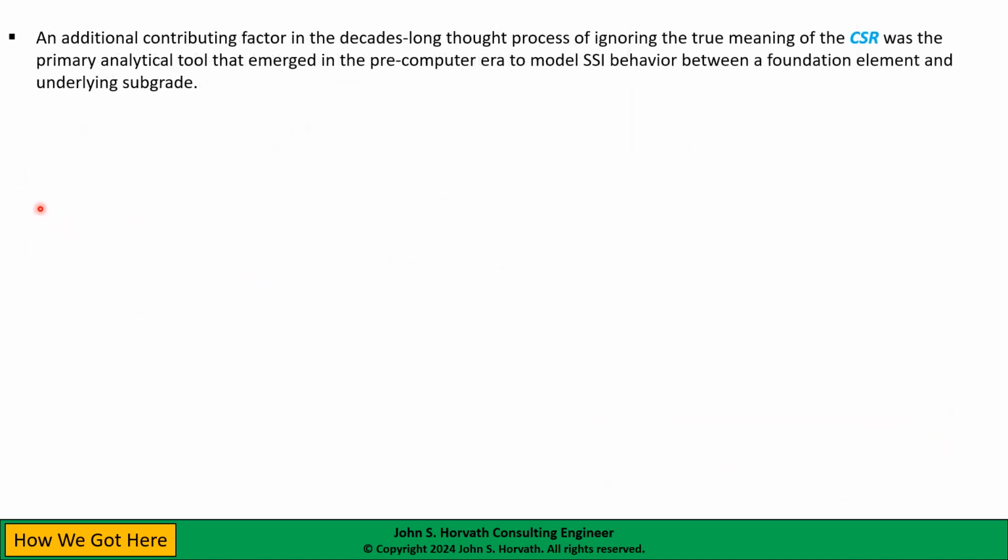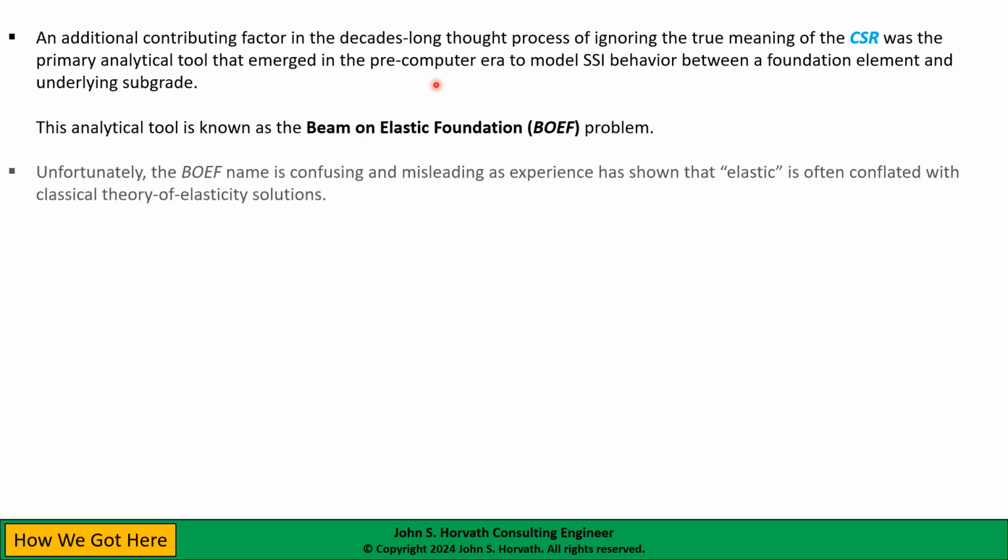An additional contributing factor in the thought process over many decades of ignoring the true meaning of coefficient of subgrade reaction as a calculated problem parameter was an analytical tool that emerged in the pre-computer era to model this soil-structure interaction behavior between a foundation element and the underlying subgrade. And this is known as the beam on elastic foundation problem.